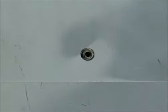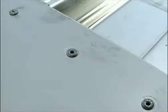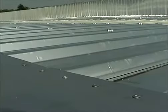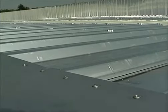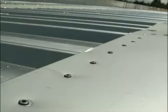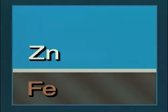Obviously, galvanic corrosion can be prevented by keeping the metals dry or electrically insulating them from each other. However, stainless steel rivets could be used on aluminium if its relative surface area is so large that the current density will give a tolerable thickness loss of aluminium.